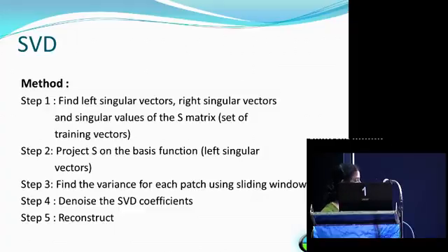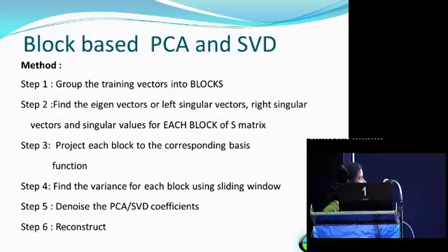Again, apply and reconstruct. In block-based PCA and SVD, instead of going by patches, I have taken groups of patches formed into blocks. And the similar procedure is done. For the blocks, I have found the principal component coefficients. Then I denoise the coefficients. Finally, reconstruction.